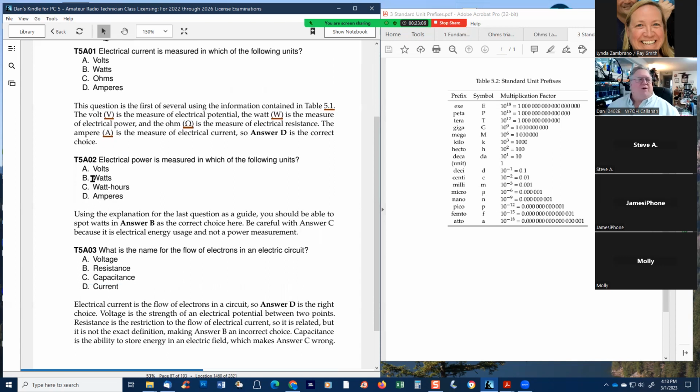That's what we pay. We pay for electricity for our homes by kilowatt, by 1,000 watts, for an hour is the equivalent. But watts is how much power. When you look at your hair dryer, it's often 1,200 watts. You can run one of those in a circuit. Two of them, you'll pop the circuit. It's too much power. So electrical power is in watts.